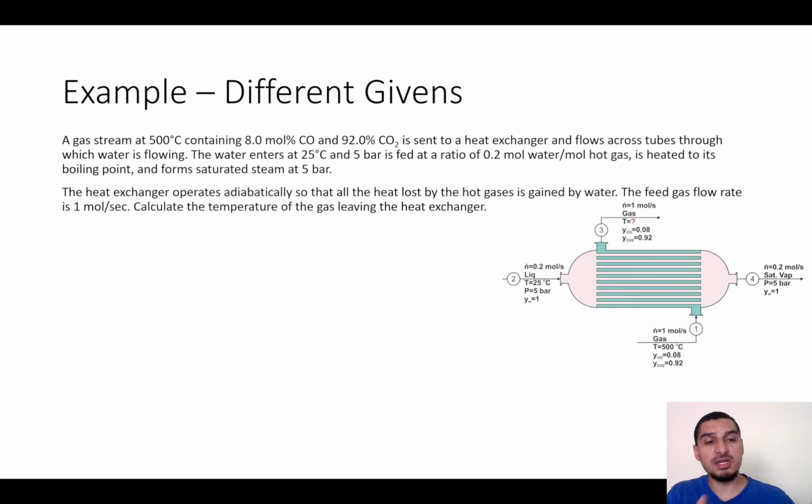And instead of installing a heater for the cold stream and a cooler for the hot stream, we let the two streams exchange heat. So I'm not spending money on heating or cooling. I am making use of the difference in temperature. So this is a hot stream that I want to cool down.